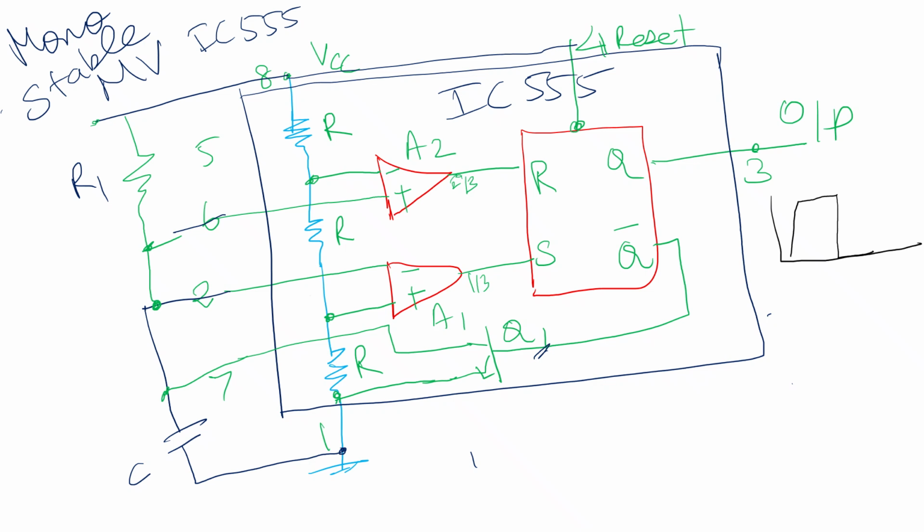The time constant for this resistor capacitor combination determines the length of the pulse. So it is used to generate a clean pulse of correct height and duration for a digital system. This is also used to turn circuits of external components on and off for a specific length of time. It is used to generate delays. They can also be cascaded to create a variety of sequential timing pulses. These pulses can allow us to time and sequence a number of related operations.